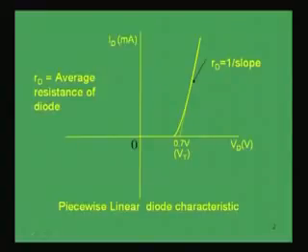The piecewise linear assumption has to be made in order to correctly model the diode. Now, in this case you see that up to 0.7 volt the current is 0 and then it is rising. So, we can assume that up to 0.7 volt it is 0, and then in this portion it is exactly a nonlinear characteristic, but when the current rises after some time you see that it is rising almost linearly.